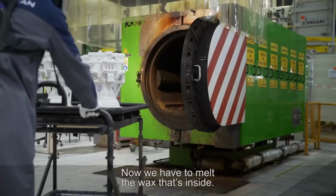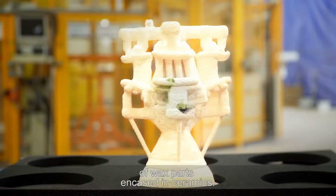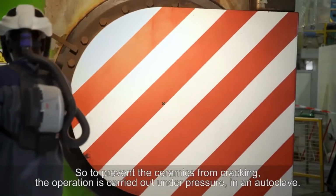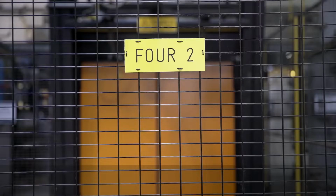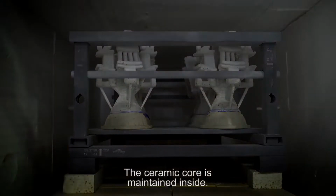Now we have to melt the wax that's inside. It's a delicate operation because the clusters are composed of wax parts encased in ceramics. The wax will expand in the heat, but not the ceramics. So to prevent the ceramics from cracking, the operation is carried out under pressure in an autoclave. Then a cooking operation hardens the shell and burns all the wax residue. The ceramic core is maintained inside.